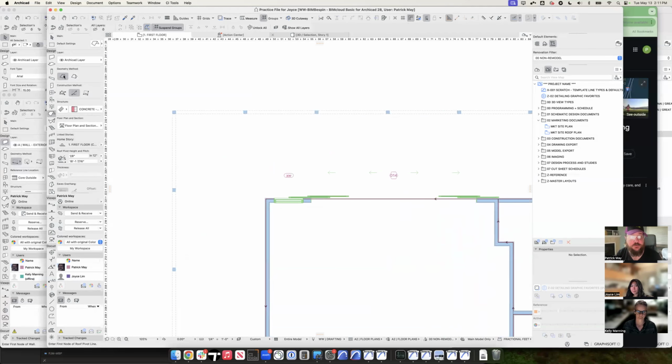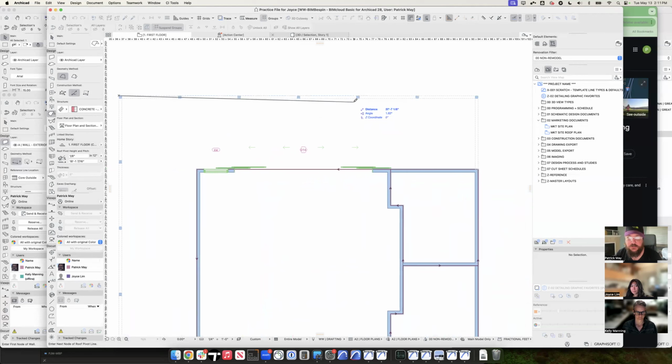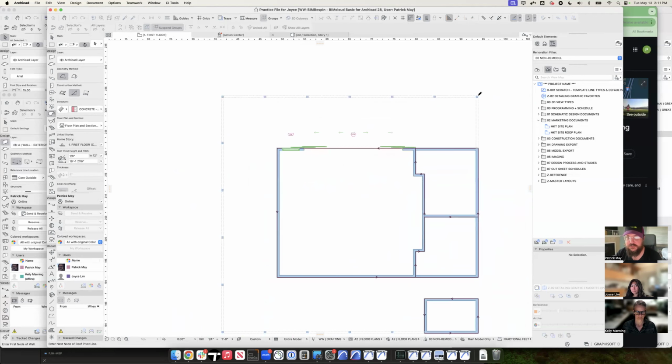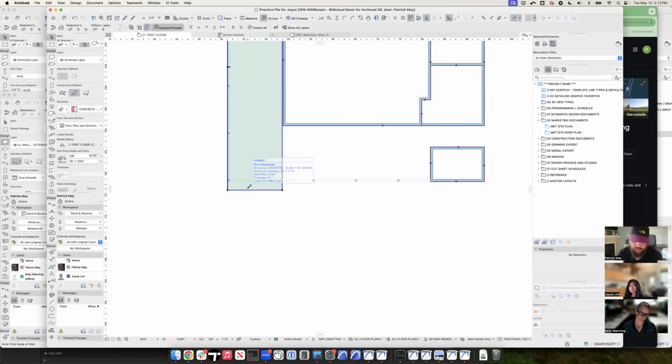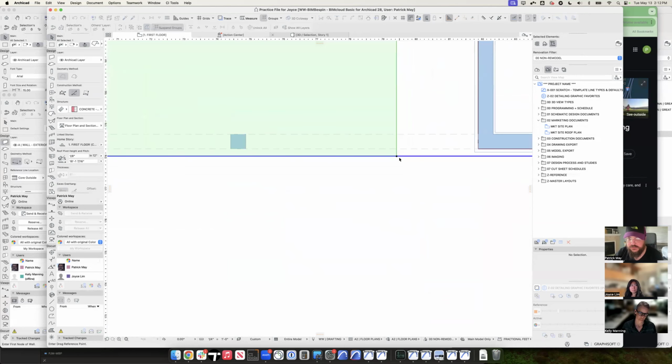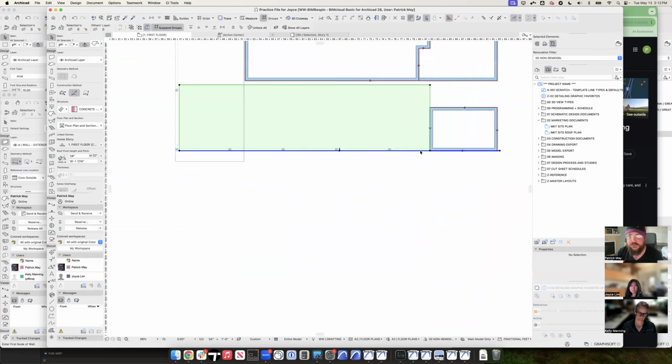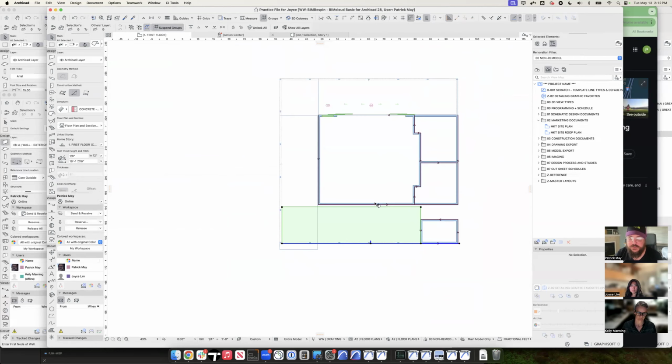For the single plane roof, I'm just going to put the reference line here to the outside. It doesn't really matter how long that reference line is, but we're going to draw it there. Then that little eyeball angle symbol is which direction is sloping upward. So I'm going to slope it up this way, and I'll draw it to here. Now if I mirror this across at a 45-degree angle, we'll do that one more time. Let's get this in the right position here. All right, so now we have a roof on each of these faces.